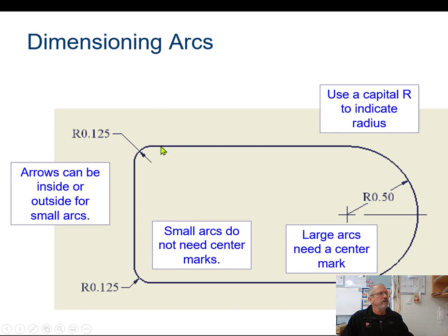Here's a small radius. This is a fillet and round. Now, normally what you would do on a drawing, especially if it had plenty of rounds and fillets, this is a round because it's convex, okay? So normally what we do is we would just write down a note: all fillets and rounds are 125 thousandths unless otherwise specified. So over here, this is what I was talking about earlier, is that your leader can come from the center point and go out.